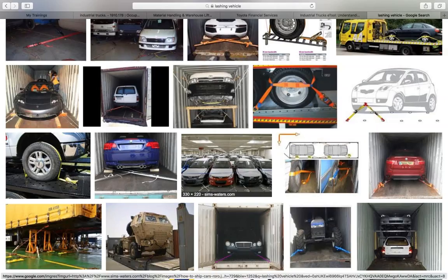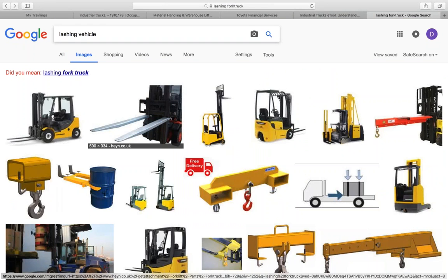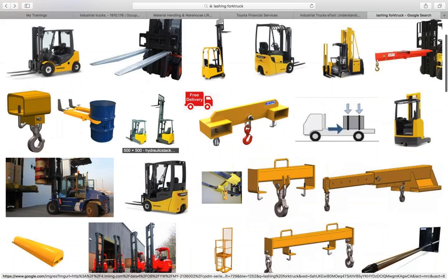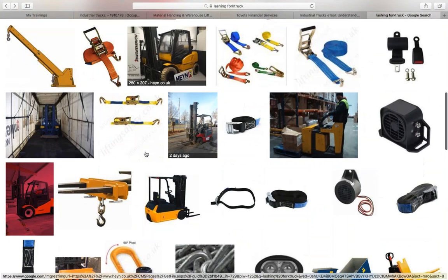And then in addition to that, we also know that the forklift may be used to carry pieces of rigging equipment as well. If we use that method, we're going to wind up putting the slings either around the forks or a spreader bar. The biggest thing is we may have to use a hoisting device also. So the biggest thing is reading that manufacturer's instruction manual, to see if we can go over the forks, to see if we have to make any considerations, to see if we need to put some type of hook or attachment made by the manufacturer in place.